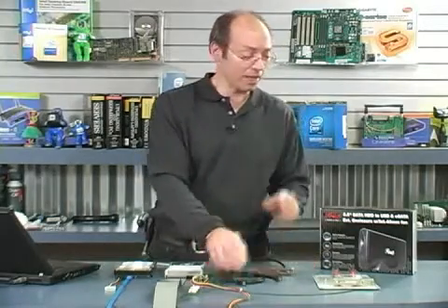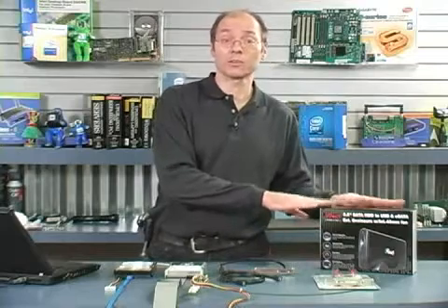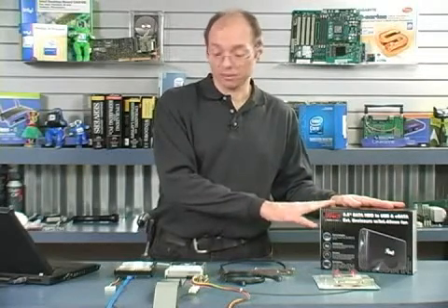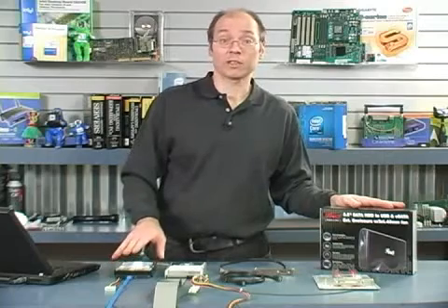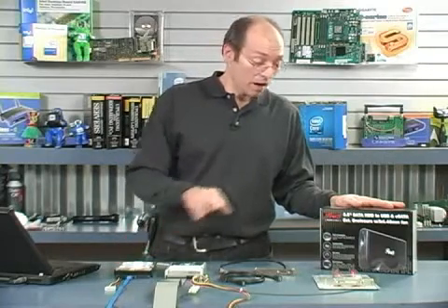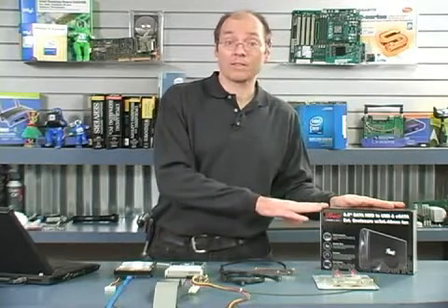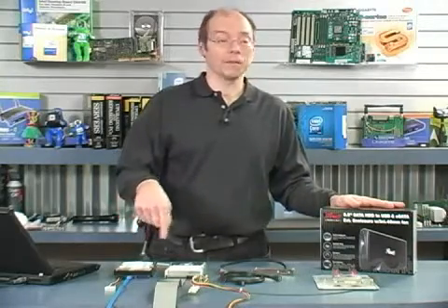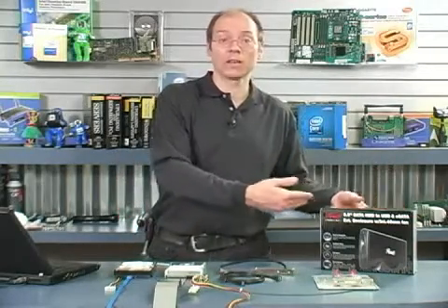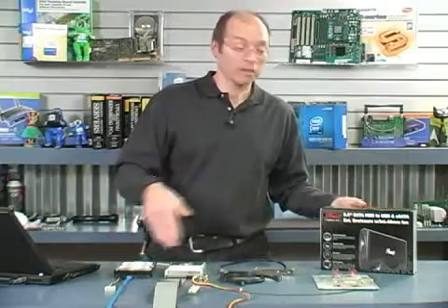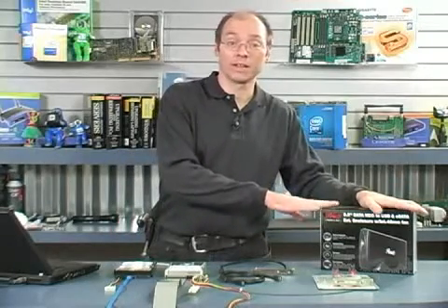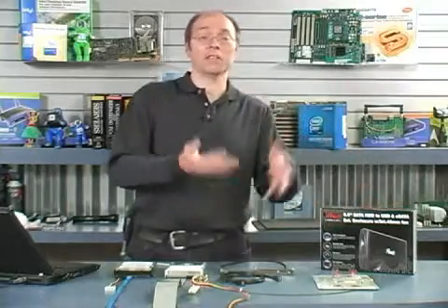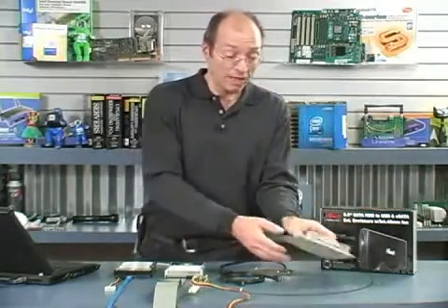Virtually all of the external enclosures that support eSATA only do so at the 1.5 gigabit per second rate. So even if you have a 3 gigabit per second drive like this one, it's only going to work at 1.5 gigabits per second via eSATA. Now here's where knowing about that jumper may come in handy, because if you build it and it doesn't work, you may have to install the limiting jumper depending upon what type of circuit board is in the particular enclosure that you're using.